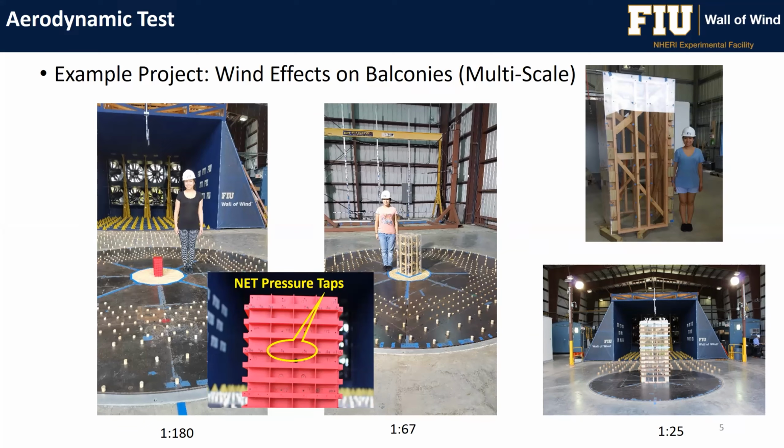Again, going back to my previous comment, there's a lot more you can do when you increase the size of the model, and we can study in detail the different smaller elements, building components and cladding. And at the same time, we can consider the Reynolds number effects, where we have a larger model, and that corresponds to higher Reynolds number.